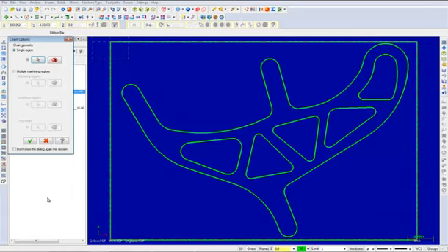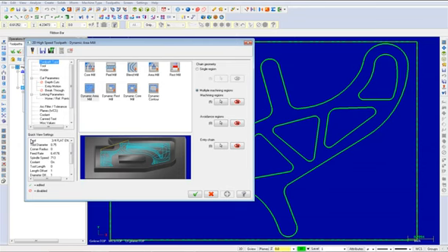In the Chain Options dialog box, enable multiple machining regions to instruct Mastercam to machine all the chains. You can now select the OK button to exit the Chain Options dialog box. In the Toolpath Type page, select Dynamic Area Mill as shown. We will now select a 3/8 chatter-free end mill from the library and set the tool parameters.